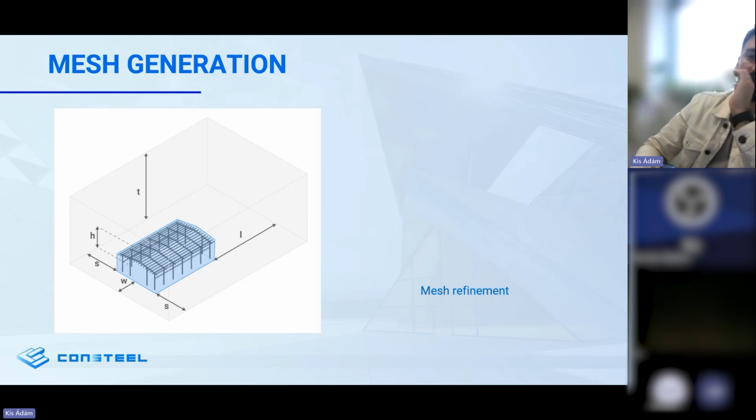And speaking of pre-processing, I would like to highlight one specific utility of OpenFOAM that makes a key difference between the world of mechanical finite element analysis that we are used to and computational fluid dynamics, and this would be mesh generation. For every simulation case and for every building, and for every direction within a finite domain, the building needs to be introduced in this computational setup. Following this, the mesh must be refined to create a negative imprint of the building, and these steps are essential to accurately compute the pressure and velocity fields within these cells to a required level of precision.